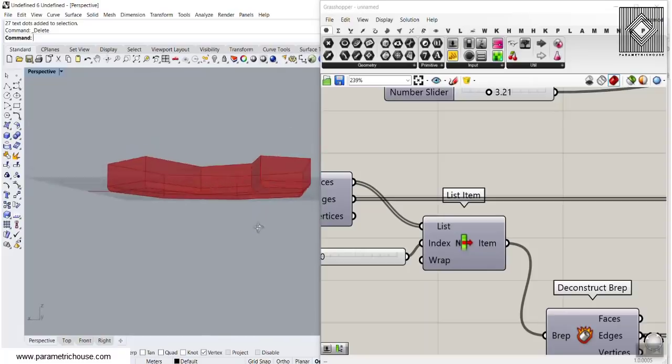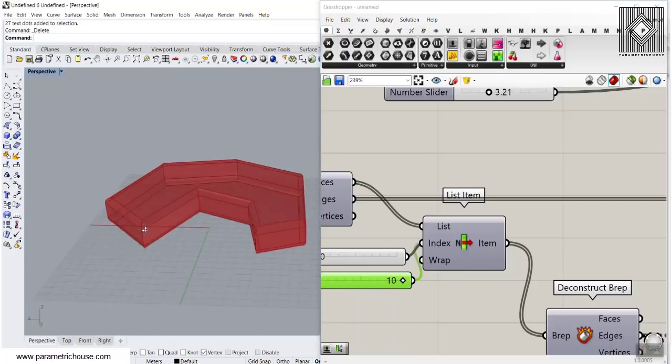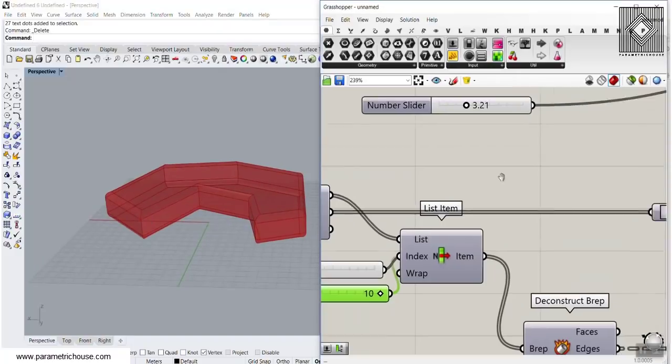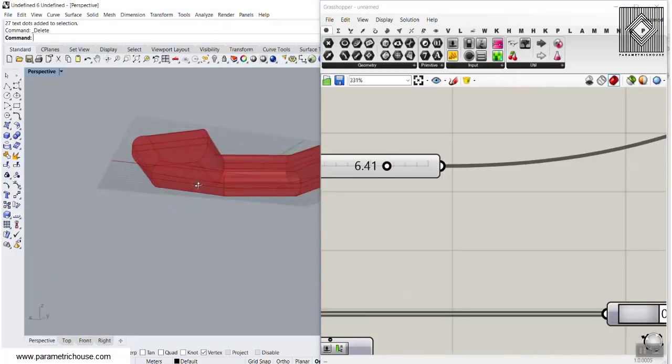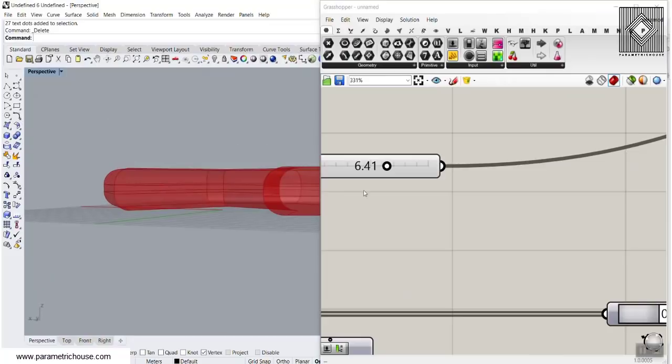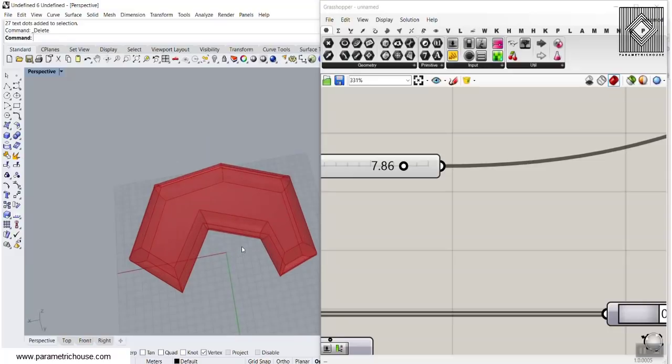So you can see that we can do that because of the groups. If I give this a 0 and a 10, you can see that we can also have fillet edge on the top and the bottom. So let's just do this and produce the results. You can see that you can just reach a point they intersect, so that's perhaps going to give us an error. So just be careful about this and put that on your model.